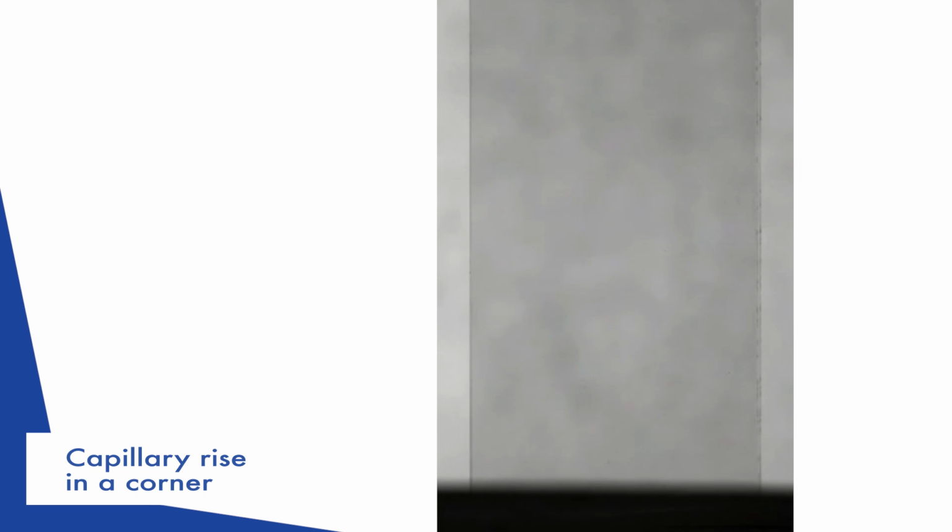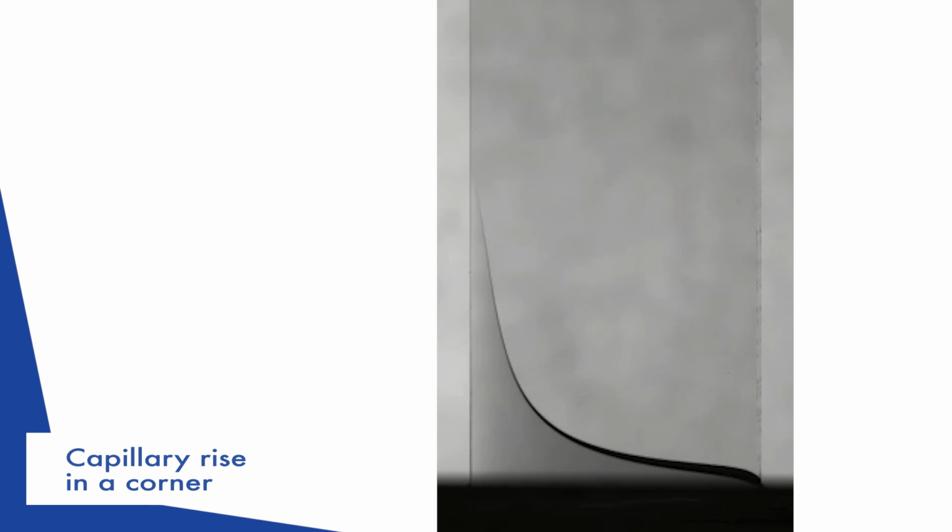Capillary rise between two plates forming a wedge is especially spectacular since the distance between the plates vanishes at the corner, making the rise at that place extremely high. By using transparent glass, we can follow the profile of the rising meniscus within the wedge, which is found to be hyperbolic, as first described by the mathematician Brook Taylor in 1712.